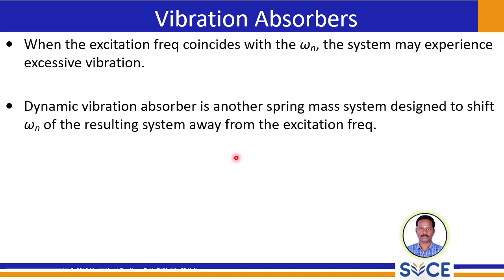This occurs when the frequency of the external excitation force coincides with the natural frequency. When this happens, the system can experience excessively large amplitude of vibration, which can lead to noise, discomfort, and structural failure.